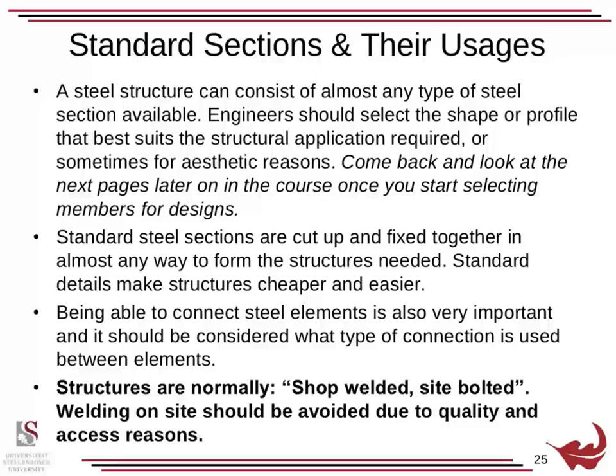And then what's a lot easier is that standard details make structures cheaper and easier. So if you use standard details, the work for the guy making the steelwork becomes quicker and faster. It might be a slight bit heavier if you use standard details rather than redesigning every connection, but normally the final cost of a simple structure is cheaper than a complex structure. Being able to connect steel elements is also very important. You should consider what type of connection to use.